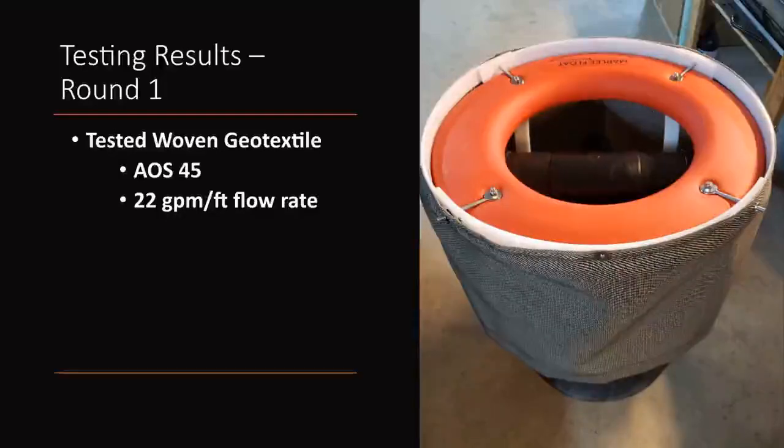We have gone through several rounds of testing with the intent of coming up with a system to meet NJCAT protocols. Our first round of testing used a woven geotextile that had an apparent opening size of 45 microns and a flow rate of 22 gallons per minute per square foot.